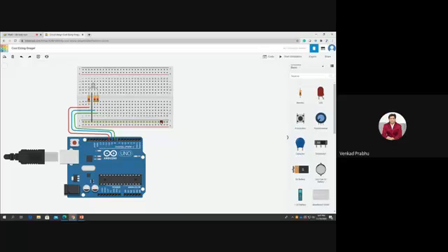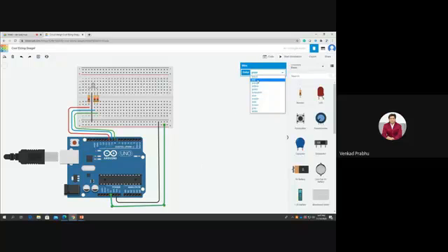Okay, for the negative and the power supply, here we have given the cathode to the negative slot. From any slot here, take a wire, move down and give it to the ground pin at the bottom, and change this into black color. So negative goes to the board negative, which is ground. For the positive, which is the power supply to the board, from this positive pin go down and at the bottom you can see 5 voltage, so give it to the 5 voltage, which gives 5 voltage power to the board.